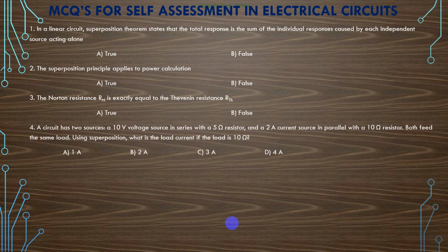Next we have the 5 ohms and here 10 ohms. How much? 15 ohms is the resultant, right? So 15 ohms total resistance and total voltage 30 volts. Now what is the load resistance? 10 ohms, which comes in series. So 15 plus 10, how much? 25. And the voltage source, how much? 30. So 30 divided by 25 is your current, almost 1 ampere, more than 1 ampere it will come.